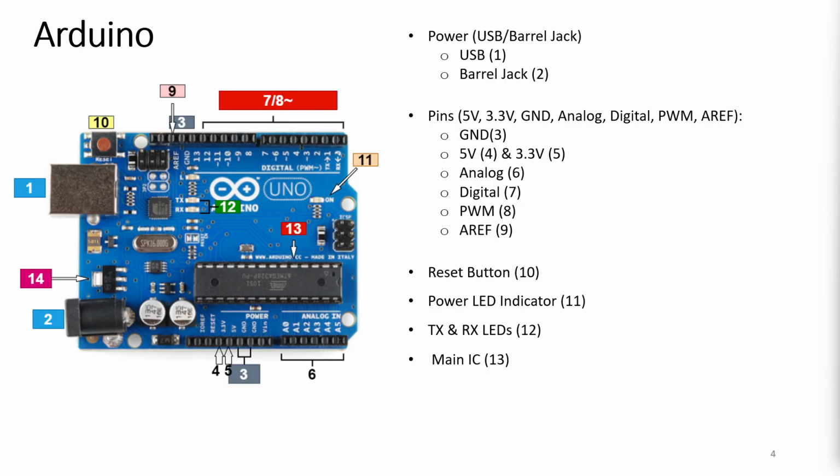This can be important as you may need to know the IC type along with your board type before loading up a new program from the Arduino software. This information can usually be found in writing on the top side of the IC. If you want to know more about the difference between various ICs, reading the data sheets is often a good idea.